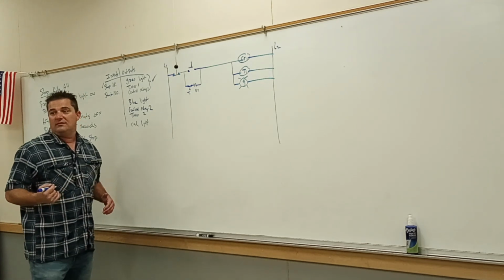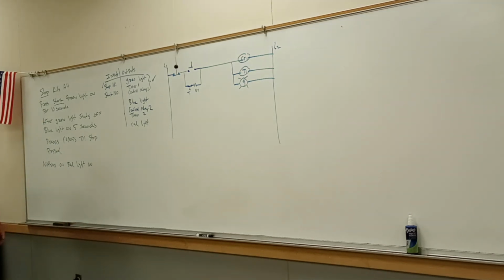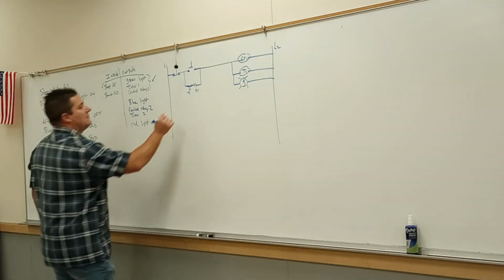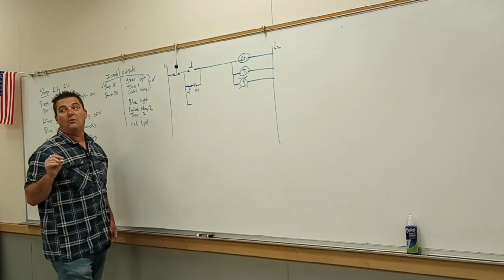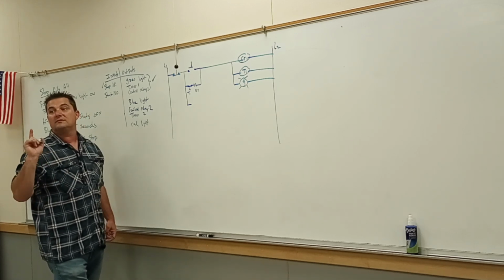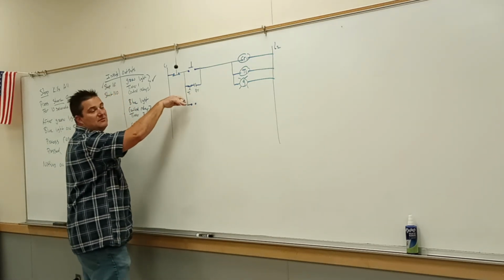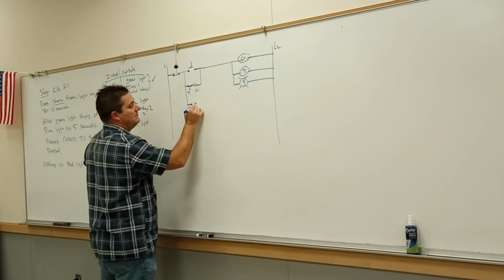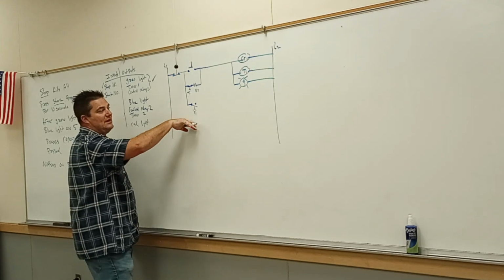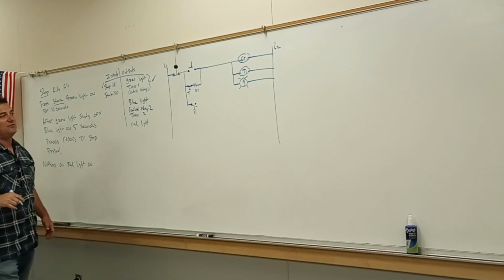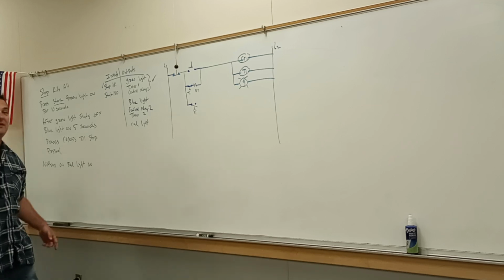What is starting the blue light? The timer. Specifically, which timer? Timer 1, right? Because timer 1 is disabling the memory, shuts that off, and then it's going to close the contacts. And when it closes the contacts, what do you want timer number 1 to activate? Timer 2, blue light. The blue light, timer 2, and the control relay.